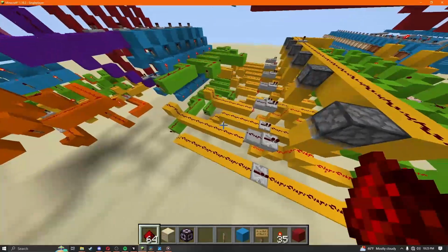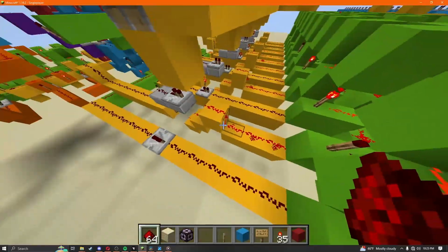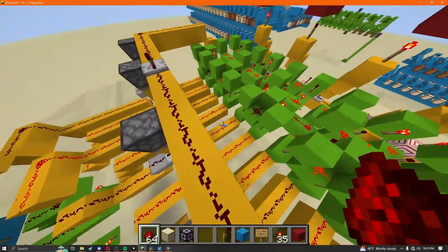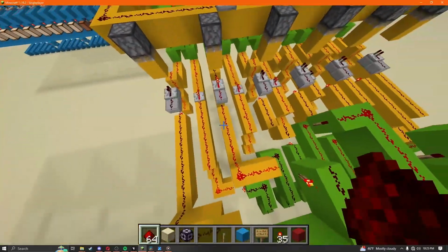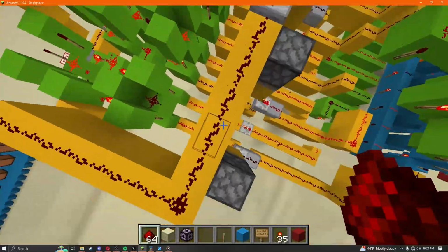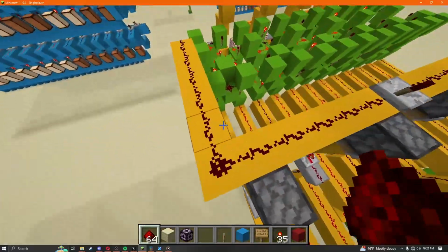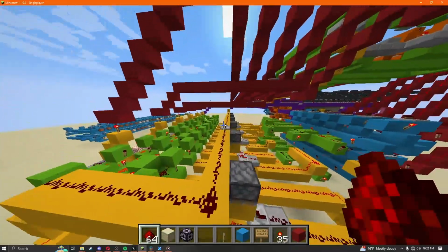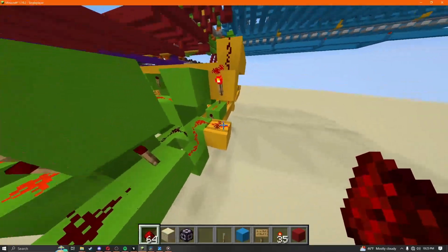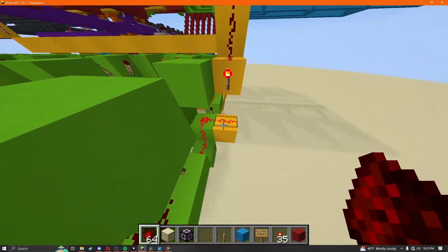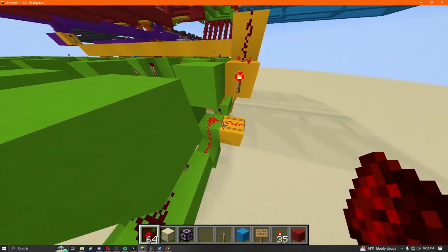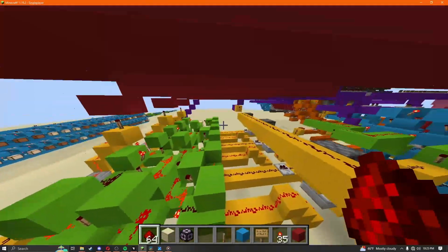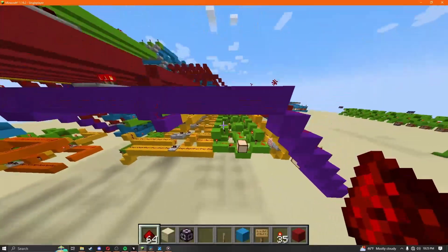So this is subtraction. What we do is we take the value, we invert it all. So if you notice, every other one of these is inverted from what it was back there. So this one's on, gets inverted, it's off here. This one's off, gets turned on here. So I guess these are all XOR gates. And as well as that, whenever we're in subtract, this is going to be off, turning this on, and we carry in the 1, which is identical to a subtract instruction.